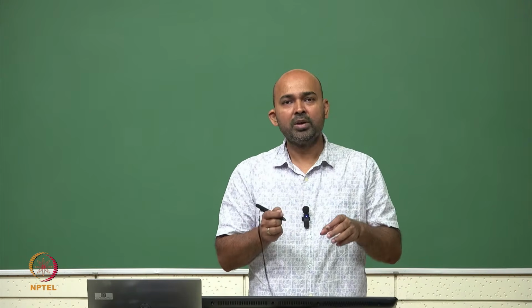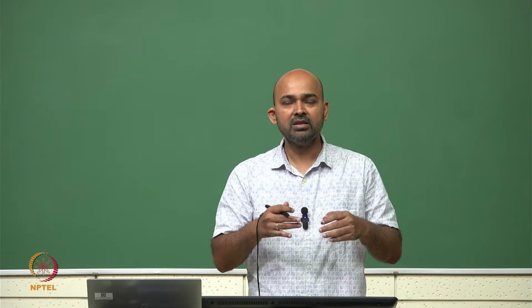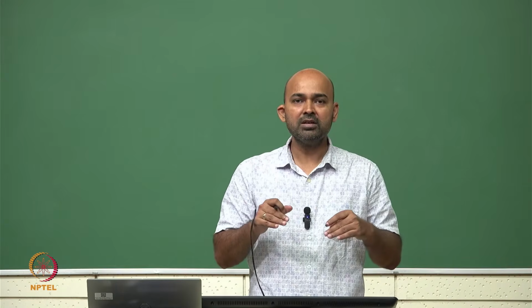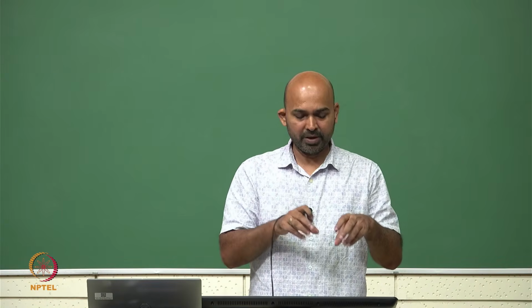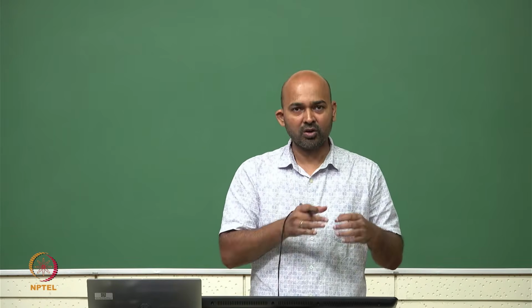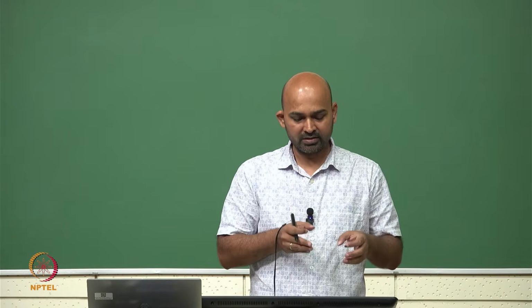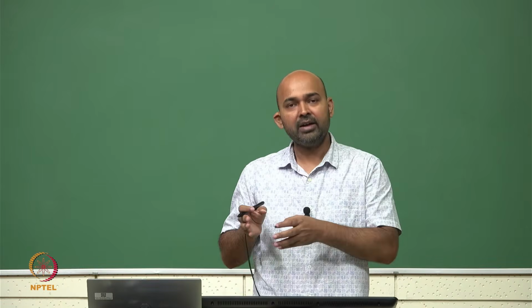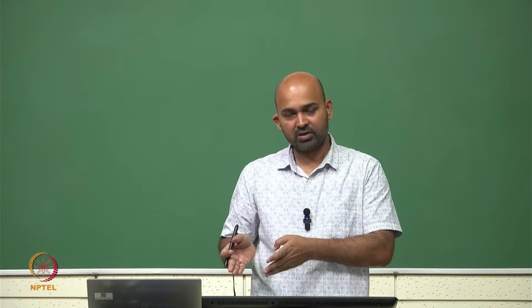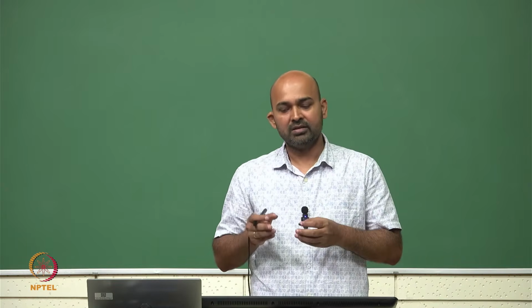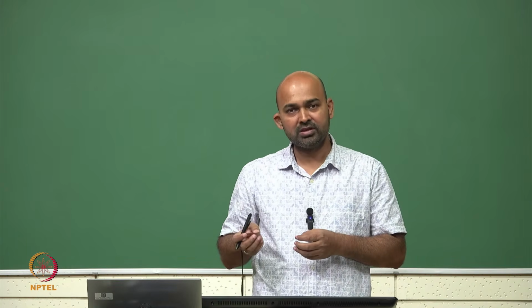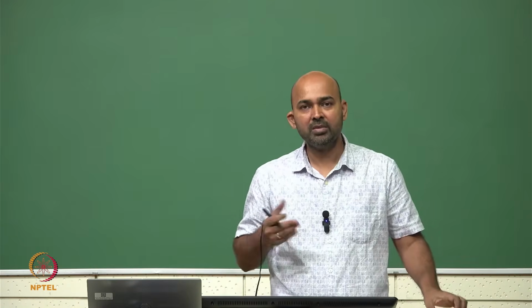And for the DC operating point, the algorithm is written in such a way that all the capacitors will be replaced by an open circuit, or its internal impedance at that particular frequency, and the inductors will be replaced by ZL or j omega L, which for DC, the 0 frequency, is a short circuit.